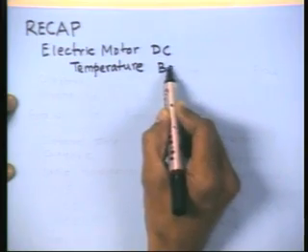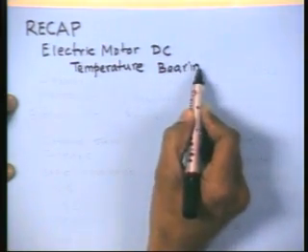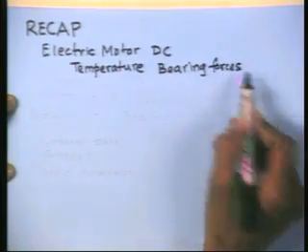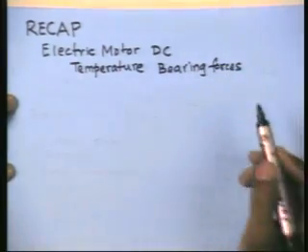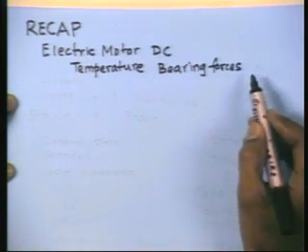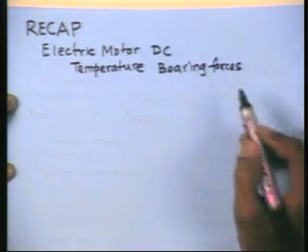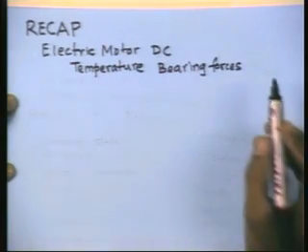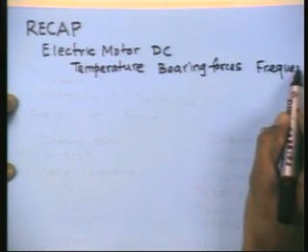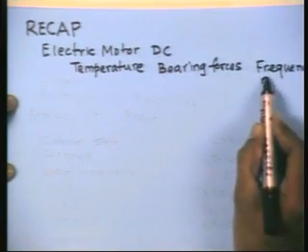He also talked about the importance of looking at the bearing reaction forces, because these are often neglected because we are looking at the requirement of the positioning and the speed and the torques. Many times we overlook important considerations like bearing forces. Then also how fast you want to move things, so the frequency response.